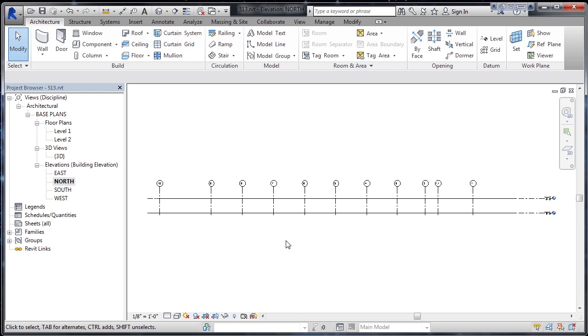It's associated with Grid A, so the elevation I bring in will sit on that work plane in line with Grid A. Now, if things don't align or you miss a step or something else isn't correctly configured, we can always use the Align tool. Now let's insert in, or in this case, we'll link in the actual north elevation 2D CAD file.